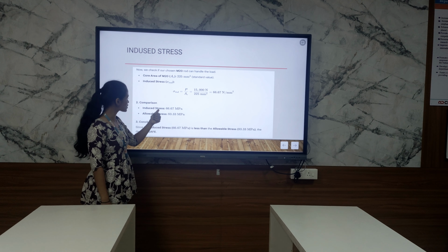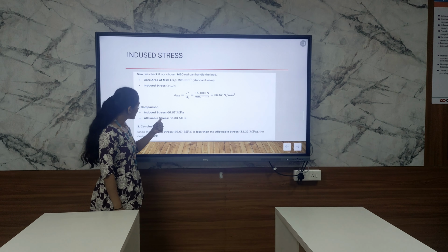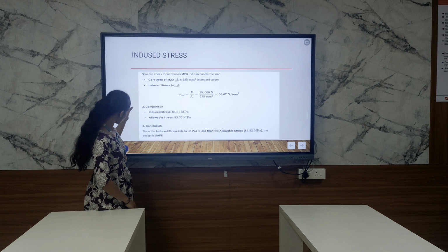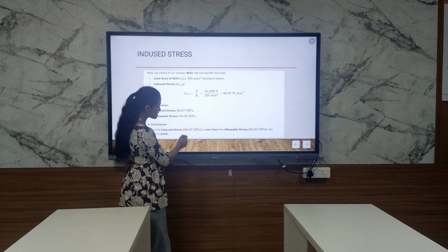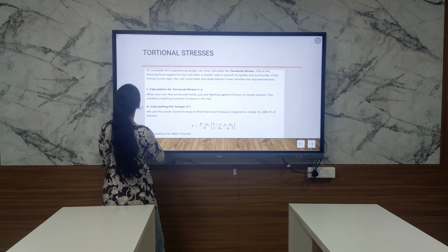Comparison: induced stress 66.67 megapascal and the allowable stress 83.33 megapascal. Conclusion: since the induced stress is less than allowable stress, the design is safe.